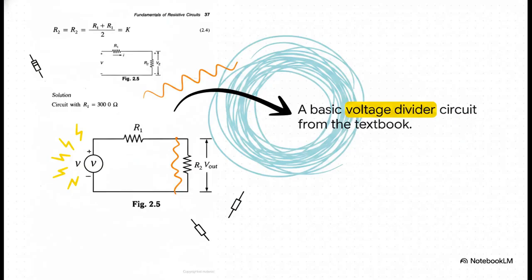To really ground that concept, here's a visual diagram pulled straight from the textbook. It's showing a basic voltage divider circuit. You can see the main source voltage over there on the left, right? And it's pushing through 2 resistors, R1 and R2, lined up right in a row. Now, the textbook shows us that the dense equation above it is actually just a formalized way of calculating that exact naturally shared workload we were just talking about. We can precisely dial down a voltage to whatever smaller size we need, literally just by picking the right size resistors to share the burden.